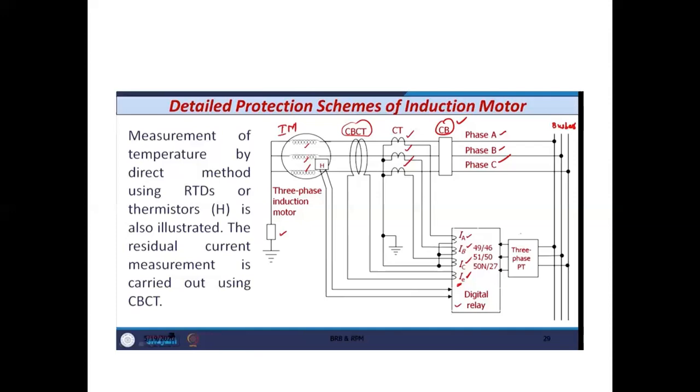You can see that along with the CTs, the PTs are also provided, three-phase PTs, because if I wish to achieve the under voltage protection, then I have to connect the under voltage relay on the secondary side of the PT.